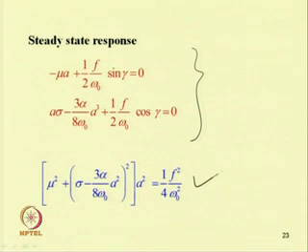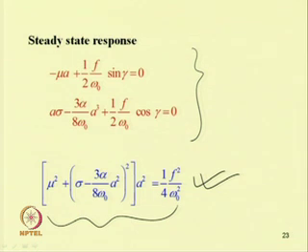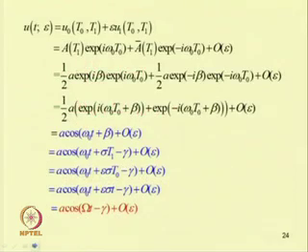So, one can get a closed form solution of this. For the non-resonant condition, one will get a steady state solution. In this equation, one can see it is 6th order in A or quadratic in sigma. Sigma is the detuning parameter, A is the response of the system. As it is quadratic in terms of sigma, one can find the response of the system by using the quadratic equation, and the overall solution of the system can be written in this form.